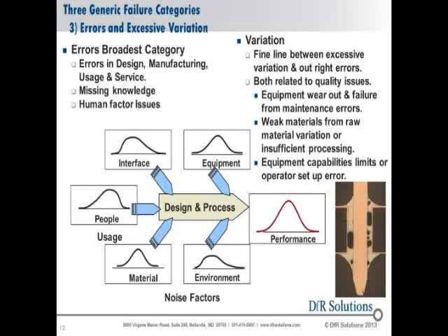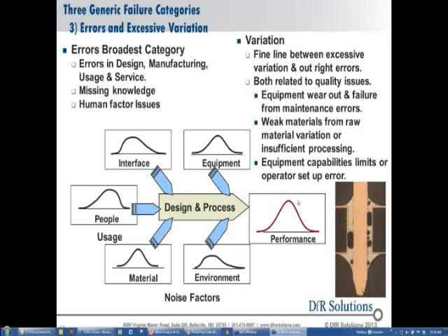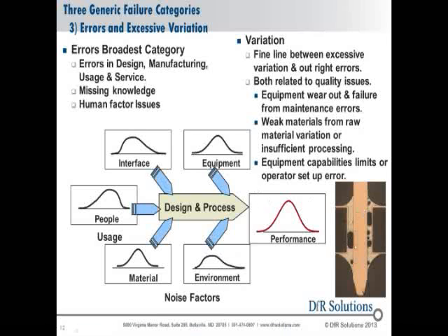So I got a little diagram here of a pin and hole solder joint, and you can see that this is not a very good soldering process. It puts a lot of air bubble voids in here, which means that this joint is not as strong as it could be. This could be a weak link because the soldering process was not optimized to prevent these air bubble voids from forming.